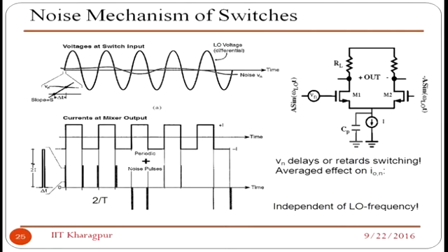That gives you a transient current pulse of very small duration, which is reflected in the frequency domain as current pulse noise. So this is a little bit of a digression from what I am teaching at the moment: you can get some switching noise in the mixer design because of the finite rise and fall time of the clock.